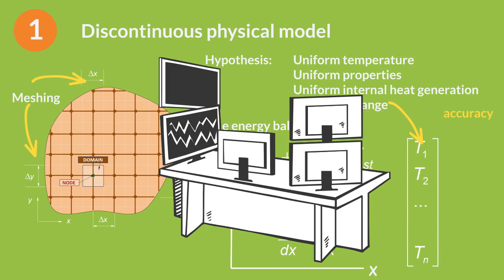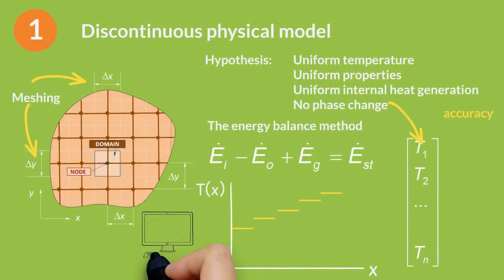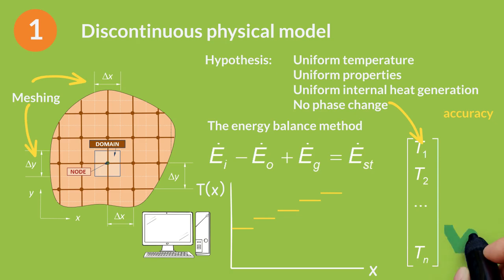However, the more elements we have, the slower the calculation and the more memory we need. In solving engineering problems, we have to reach a compromise solution between precision and the necessary computational resources. In many cases, results obtained from a coarse grid are satisfactory. Selection of the appropriate grid is a judgment that must be made by the engineer.